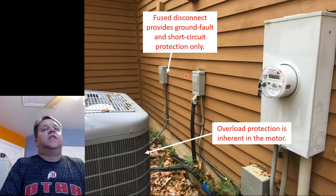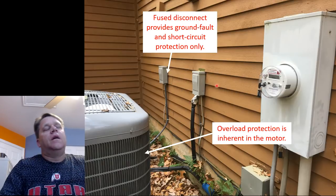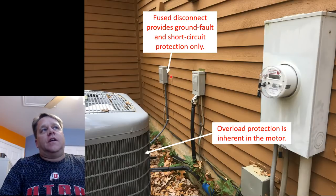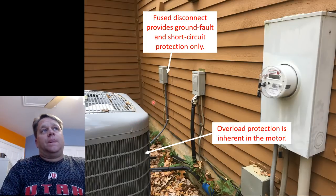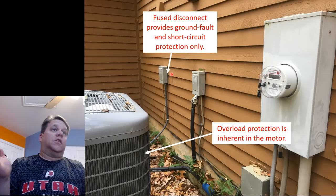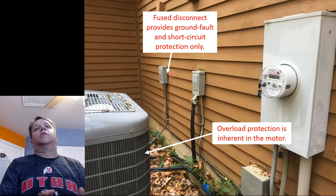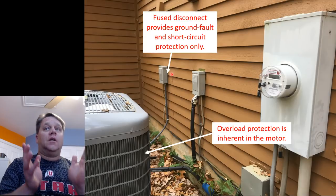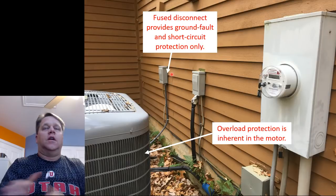All right, let's take a look at this air conditioner here. This is where people get so screwed up. I've got a fuse disconnect, and I've got my air conditioning unit. It's critical that you understand this. That fuse disconnect does not provide overcurrent protection. I know, look, it's an overcurrent device, it's a fuse, but it doesn't provide overcurrent protection, because overcurrent protection is what? Protection against ground faults and short circuits and overloads.